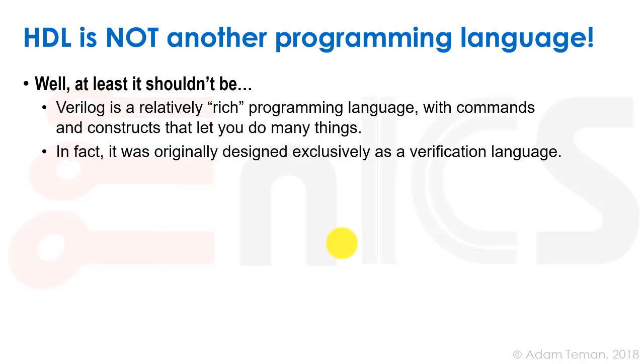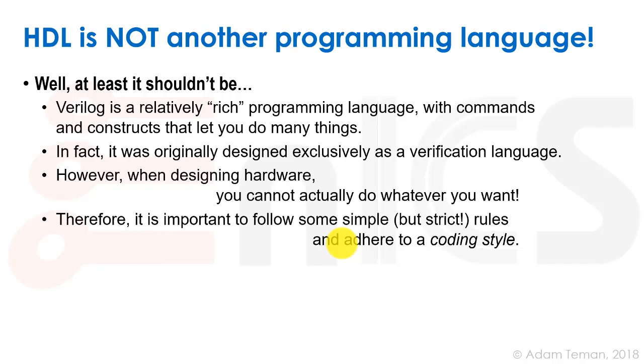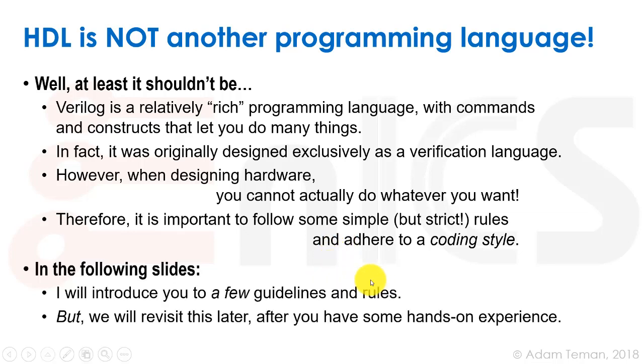Verilog is very rich. It has commands and constructs that can let you do many things, and you can buy books that show every single type of thing you can do and every difference between Verilog 2001 and Verilog 95 and so forth. It was originally designed as a verification language. There's a lot of things you can do. But when you're designing hardware, you're designing these DUTs, you can't actually do whatever you want. It's very important to follow these rules and coding styles to make synthesizable code.